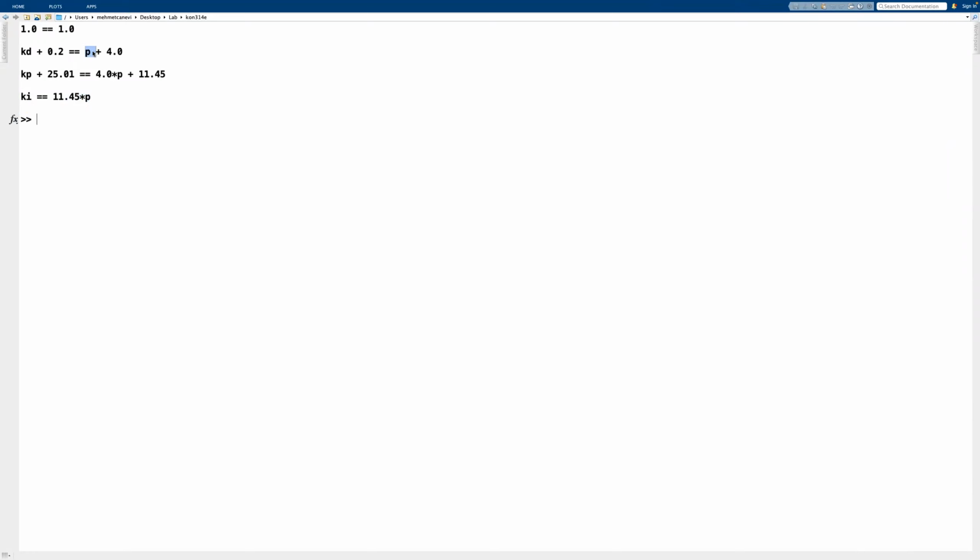So we will choose KI because in this case it makes sense: I need to check what the stability of the whole closed loop is going to be. Since one of the poles is S plus P and the other remaining poles are already stable, on the left half plane, I should be careful about the value of P. And since P is directly related to Ki and the positiveness of P ensures stability, I can conclude that Ki positive is going to end up in stable solutions.